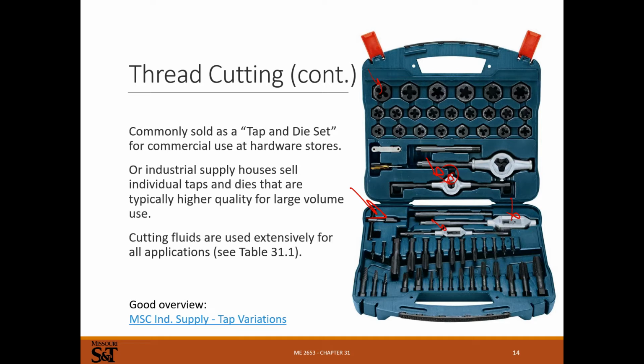So what I recommend is buy a really nice set of taps with the bits that come with them, because you're always going to end up breaking those bits out of your drill index if you don't buy bits with your taps for the common sizes. Then maybe buy a set of dies for the common sizes, and then just buy tap handles and die handles. Spend good money on those because you're going to be reusing them. Buy nice taps and dies, but plan on replacing them at some point in time. Don't buy some gigantic set, because usually you want to buy the ones you need.